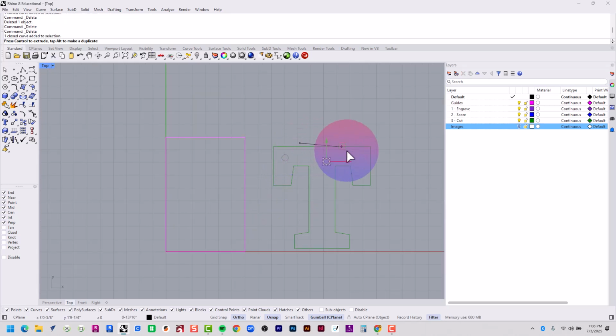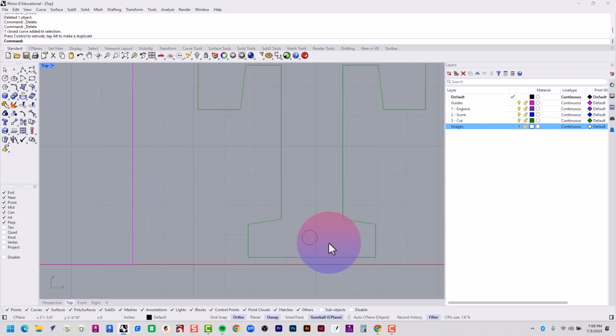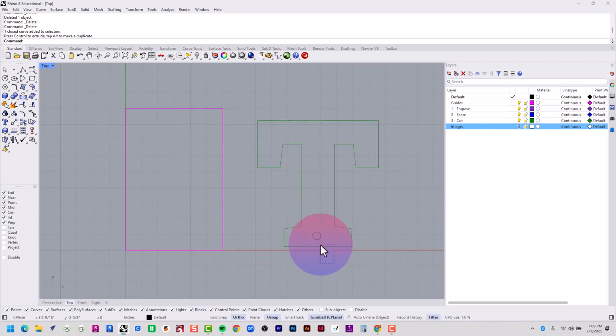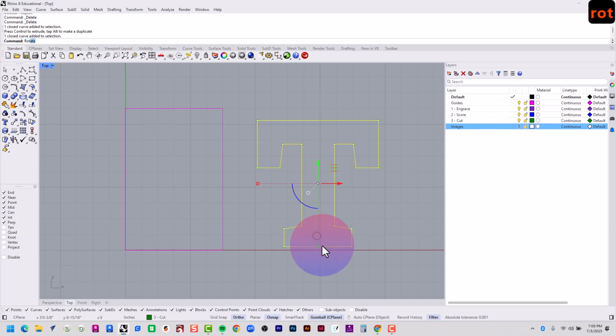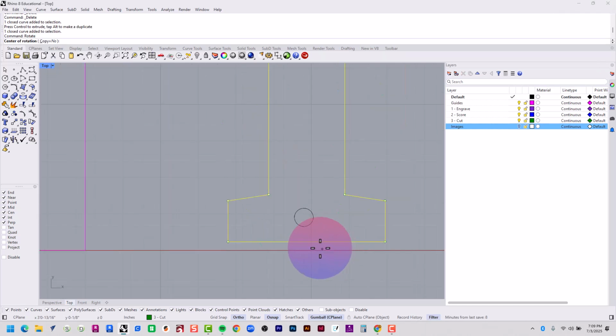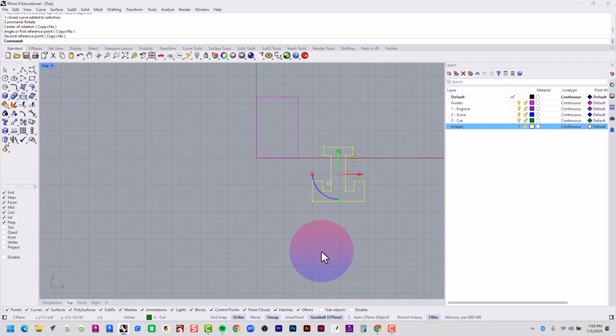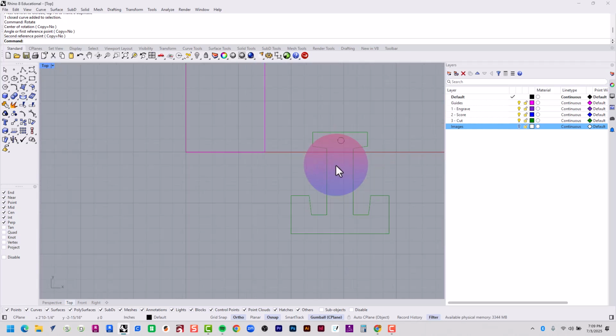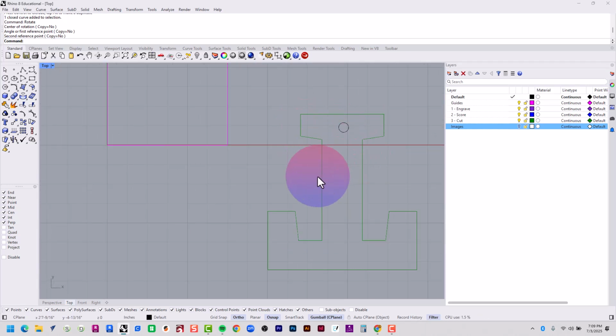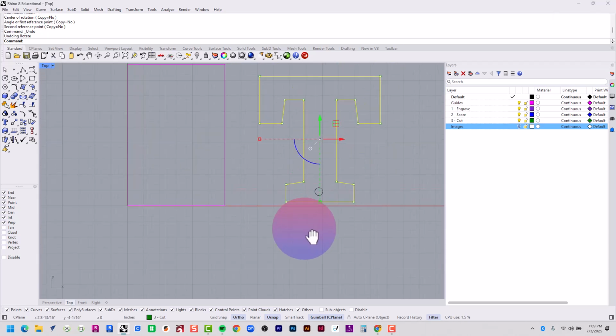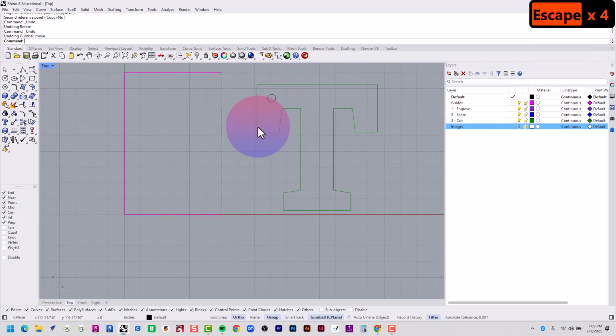You can place it anywhere you want, but if you place it up here, or down here, what's going to happen is this whole T is going to dangle. So if I were to rotate it just to illustrate that, it's going to dangle, and whoever's looking at your keychain is always going to see it dangle, and it'll be upside down like that. So I'm going to hit undo, I'm going to hit undo, and I'm going to leave it at this top left corner.